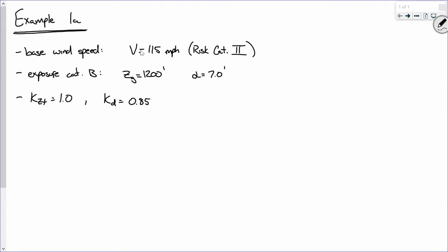Okay. So what we have to do in order to do this is we calculate a base wind pressure at each story of the building. So we would have to do this calculation 4 times, one for each story. Because you're having to do this calculation over and over and over again, it's starting to sound like a nice Excel calculation, right? Nice repeated calc. We're going to do one of them by hand, and then I'll show you the Excel file that does them all. So let's consider the 4th story, and I just sort of picked the 4th story.